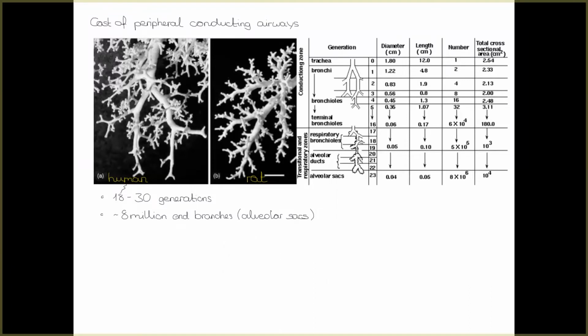So when we think about Navier-Stokes equations, for example, what number is so important? Yes, exactly. So we have much slower velocity, and at the same time we have in each individual branch a much smaller diameter, so the Reynolds number goes dramatically down. And what does that mean if the Reynolds number becomes very small? The flow is laminar. Exactly, yes, it's laminar. And actually in the extreme case, if the Reynolds number becomes even smaller than 1, at some point it's more than just laminar.